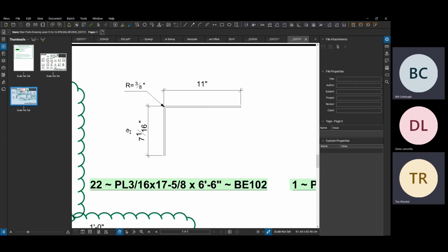Sometimes we would be sent a 7-gauge material that is not the same thickness as 3/16, but is commonly referred to as the same, in which it's not. So if they don't bend it to the correct dimensions, and now it's got to fit over something, and the inside was critical to hold, the outside was not so important. That's what drove the question.